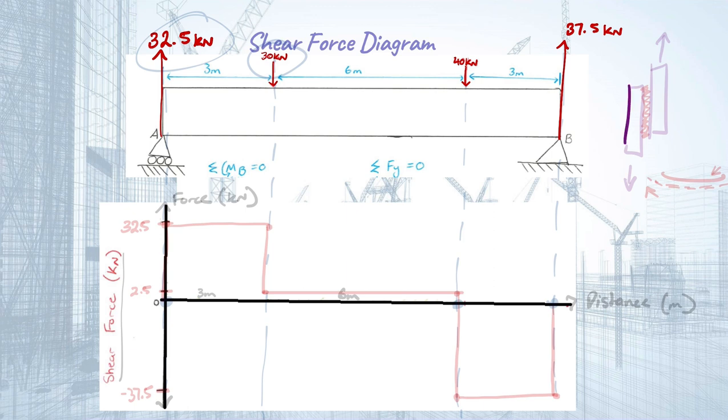So as you can see over here, if you have two things, and one's being dragged this way, the other is being dragged this way, a shear force, so that's a sliding force, will be induced along this plane here. So when a beam tends to bend, it's going to induce a shear force within that beam, as there's going to be two forces opposing. We know that this is in compression and this is in tension, so we've got those two opposing forces. So we've got that shear force acting along the neutral axis.